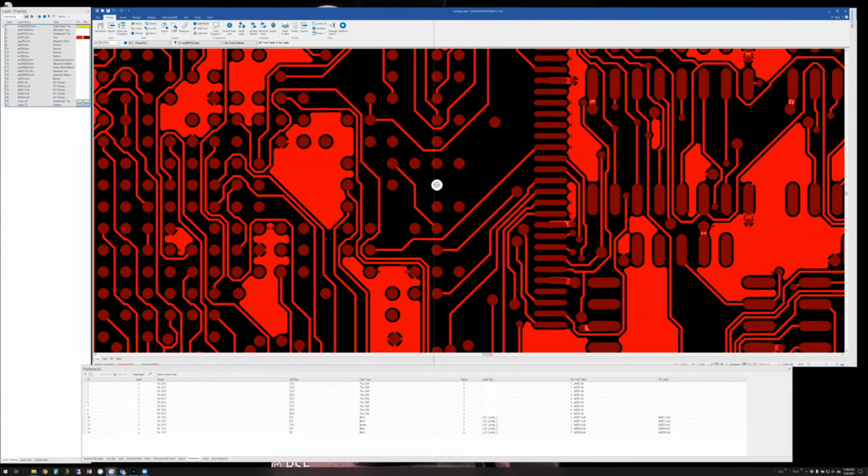Okay, so if I do a query decode, for instance, it tells me what that item is. Depending on what layer I have turned on, if it has a pad stack, it'll show me that, or if it just is looking at a decode, I can see that it's decode 36 and the size is 25. Now, if I want to do any edits, that's information I need.